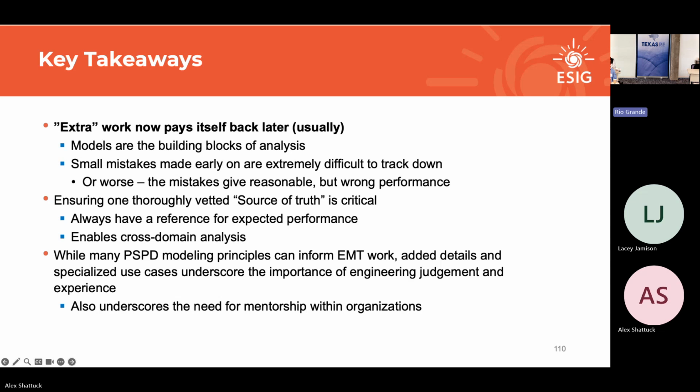In this example, not doing the extra work at the beginning really hurt. In the context of power systems, it was a cheap study, but the curtailment was the extreme cost, because that was maybe 3 months of curtailment at 50%. And it could have been transmission upgrades. So doing your due diligence now, and this is for the developers and the consultants, well, the consultants will make money on it either way, but for the developers in the room, doing these studies at the beginning is very important. It may seem like a sticker shock for the cost of the study, but the implications get more and more as it goes on, right?